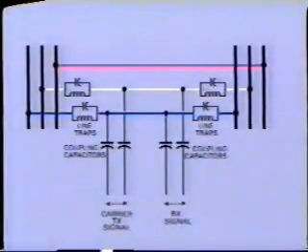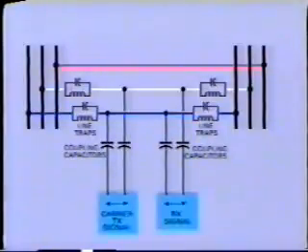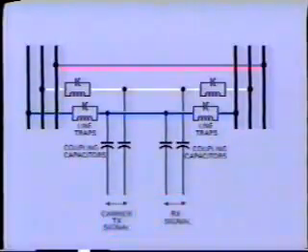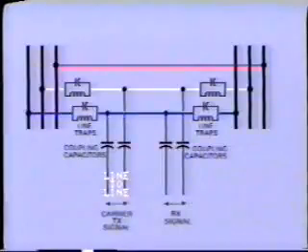An alternative scheme may use a phase-to-phase connection. As shown in this schematic, the transmitter and receiver are coupled to 2 power line conductors at each end. The carrier signal is applied line to line. With this arrangement, the requirement for line coupling equipment is doubled.